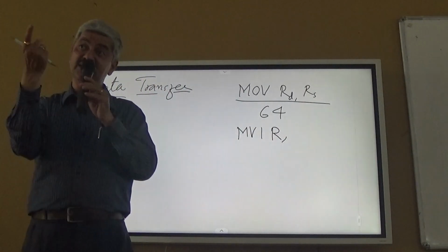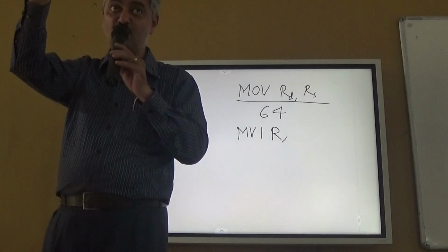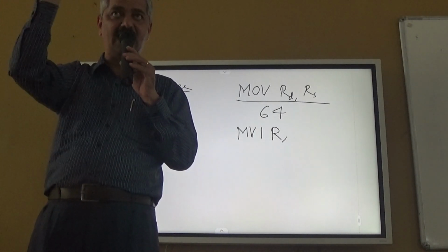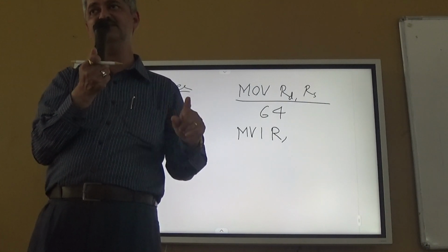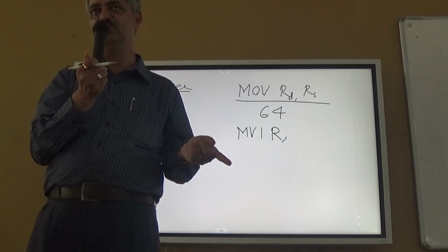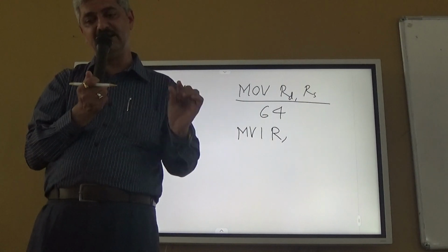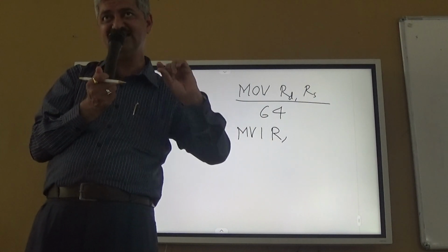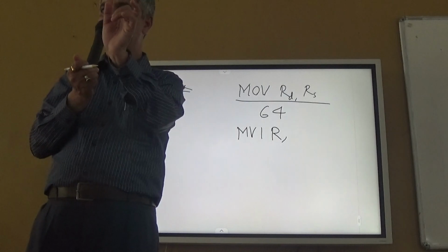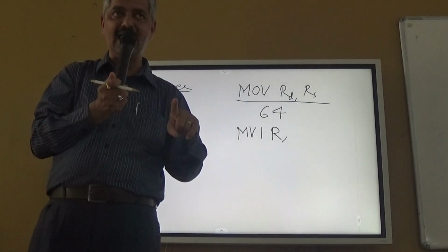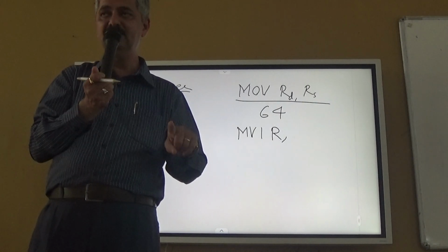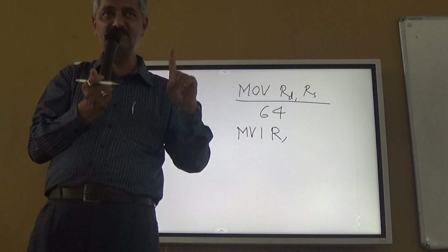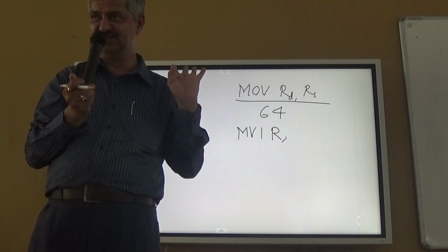One of the registers including M. So whenever we specify R in the instruction set, the instruction set has been designed to offer flexibility to include or to refer to an external location just like a register, always by the alphabet M. So MVI R includes MVI A, B, C, D, E, H, L and M. So 8 such instructions are there.